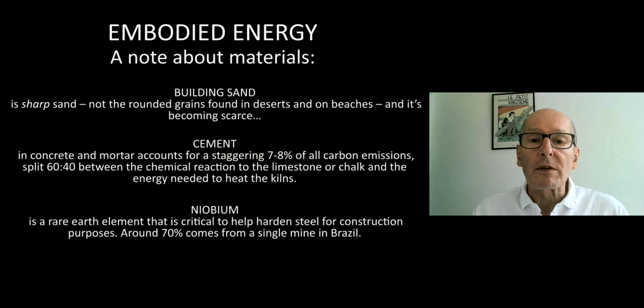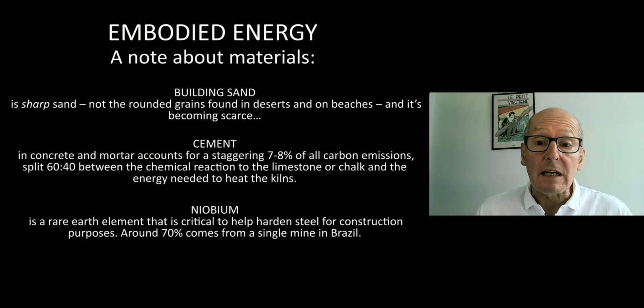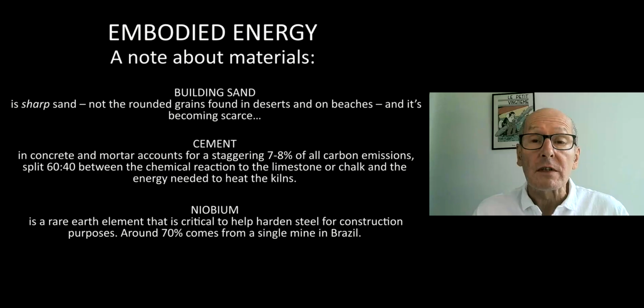Cement, and I think you're probably already aware of this, people always say that using concrete and using mortar is a problem nowadays in terms of its impact on the climate crisis. The reason is, yes, it accounts for a huge proportion of the world's carbon emissions, but specifically, as it says there, there are two parts to the process. It's the cement in the concrete and in the mortar that's critical, and one is the chemical reaction of the limestone or chalk itself when you're manufacturing the cement, and the other is, of course, the energy that you need to heat the kilns to burn it.